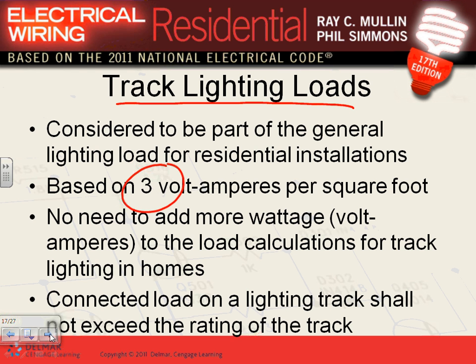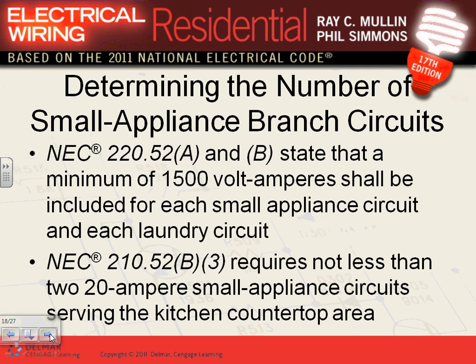It makes more sense. Did you guys do the load calculation for commercial industrial, Gary? Did you start the commercial industrial load calculation? Okay, if you haven't done that, it doesn't make a whole lot of sense. Later on, next quarter, we're going to have track lights in our commercial building, and I'm going to ask you to find a volt amp for this track light and assign a certain amount of volt amp for it.